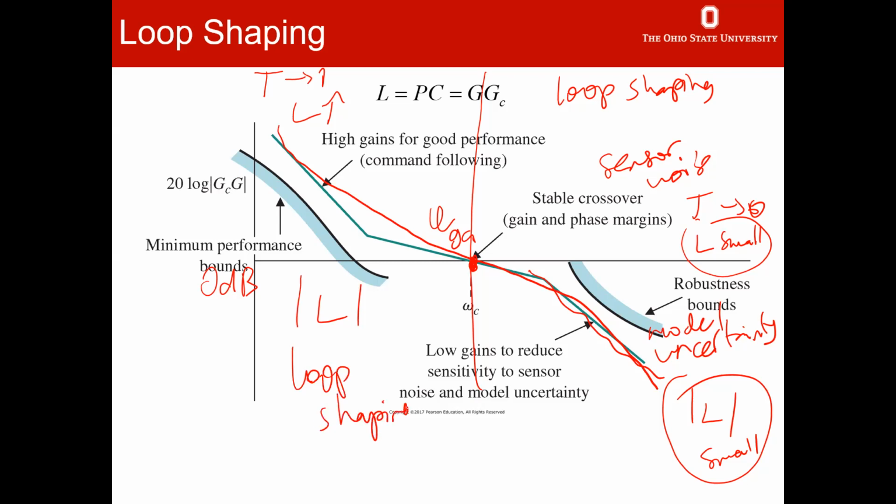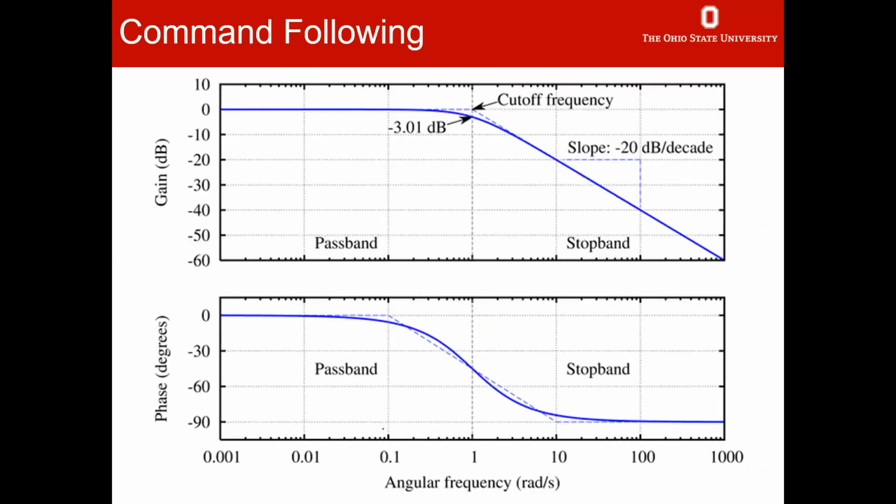So basically, all of classical control design is on loop shaping, unless we do the root locus design and concentrate on time domain properties exactly. I'm going to keep coming back to this as I do frequency domain control. This is just an introduction, okay? So basically my T is going to look like this. I'll have 0 decibels or a gain of 1 here, and magnitude of T will go to 0 at high frequencies. I want my phase to be equal to 0 degrees at all frequencies, but unfortunately it has to go down.